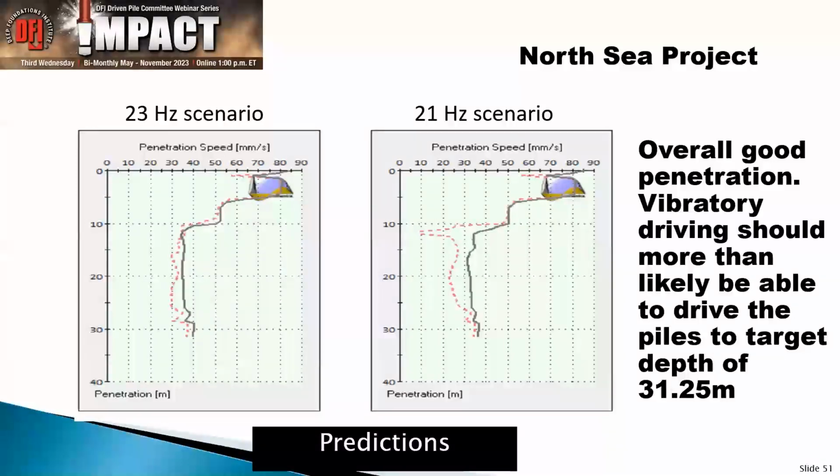But most of the time, when you pre-drill through that material, you end up with still a fairly decent estimate of your shaft friction, because it's generally a fairly short distance that you pre-drill through.